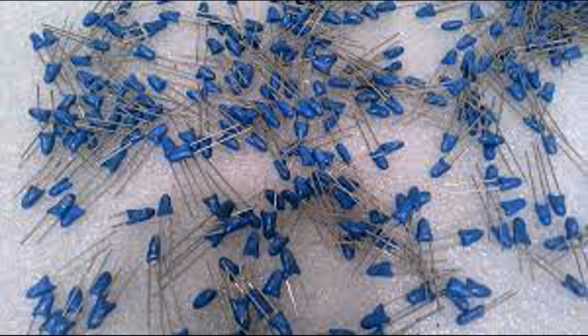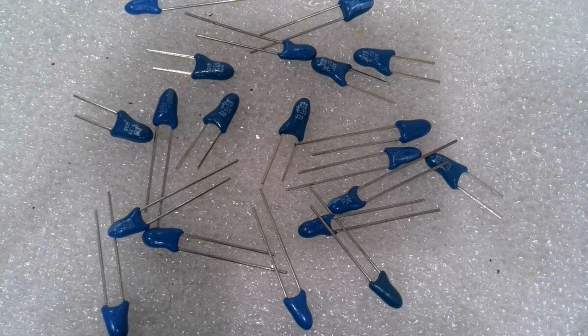Capacitance is a measure of a capacitor's ability to store electrical charge. In the case of a tantalum capacitor, the capacitance is determined by 3 primary factors. Surface area of the anode. The larger the surface area of the tantalum anode, the greater the amount of electric charge that can be stored. In tantalum capacitors, the anode is made porous to maximize its surface area, allowing for a higher capacitance in a smaller volume.